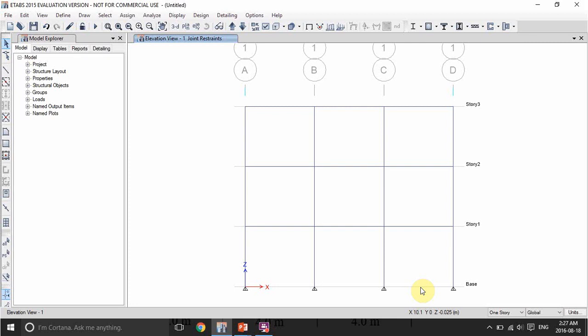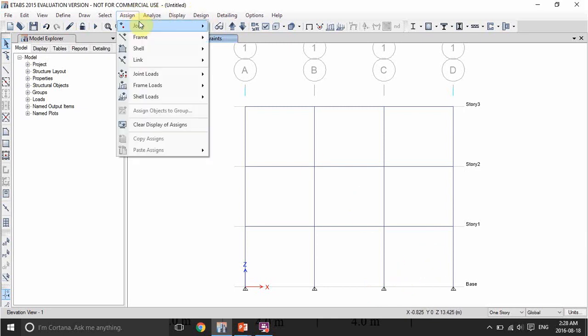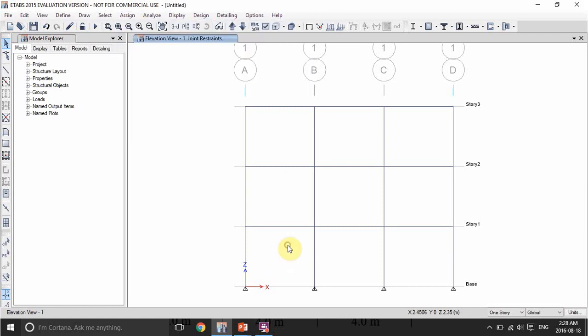In reality, the actual case is something in between. It requires some engineering sense and some engineering judgment, a discussion with the team. It depends on the numbers that you get from the soil reports provided to you as a structural engineer. You can model the supports here instead of pins and fixed supports. You can model them as spring supports, like from here. But it needs some calculations. There are many references found in literature on how to model the supports, but usually the pins are okay.